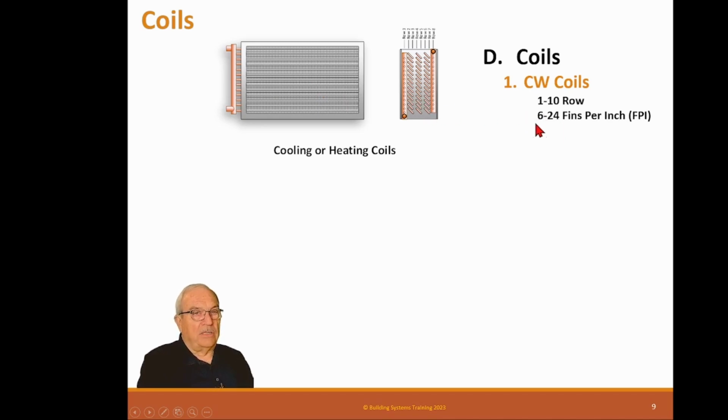I've always, on my commissioning jobs, restricted fins to 12 fin. I'd like to have 10. 10 is really good to clean. 12, but over 12, you don't need them. Now, sometimes on a reheat coil, maybe they'll go to 18, but never 24. I don't know why the manufacturers even make them.